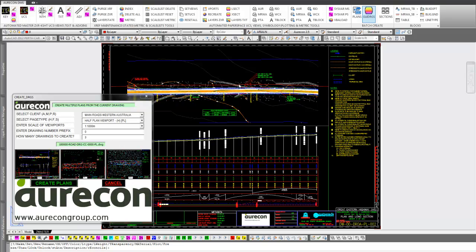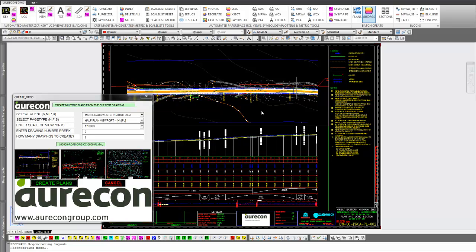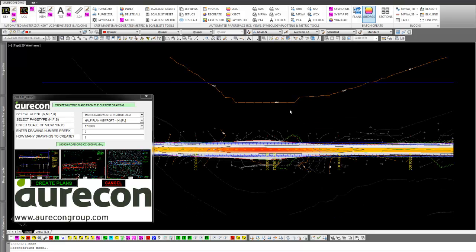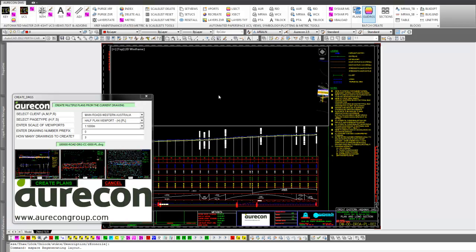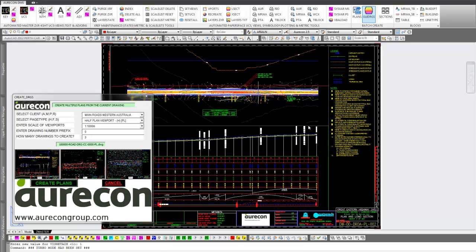Again, that text should disappear, should mask on the next drawing number, which will be number 3. It'll pop over to model space momentarily, and update all the UCSs and views from the imported information from the key sheet. Somebody could be working on it concurrently. It doesn't really matter. That's been reset. You can see the red for the cut in the hill from the depth contours. That's been aligned, reset, masked on the text.